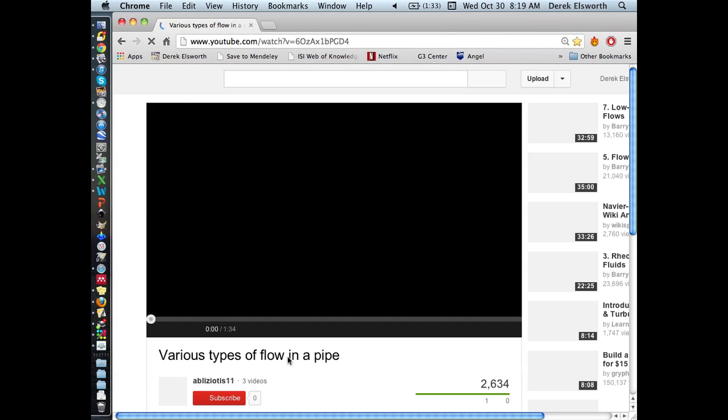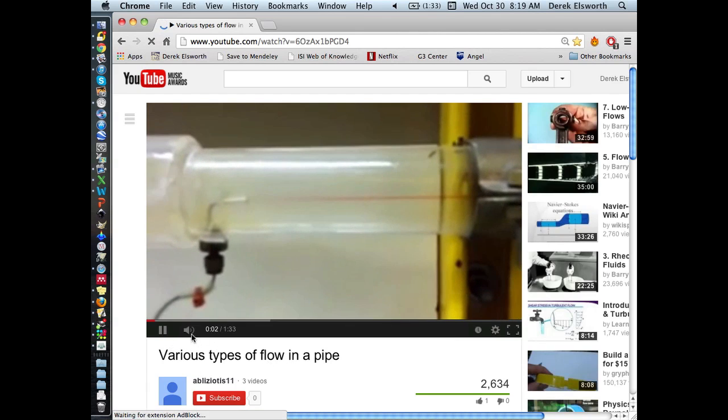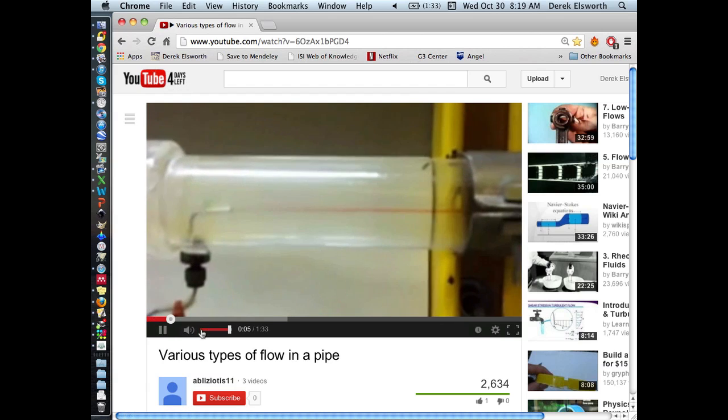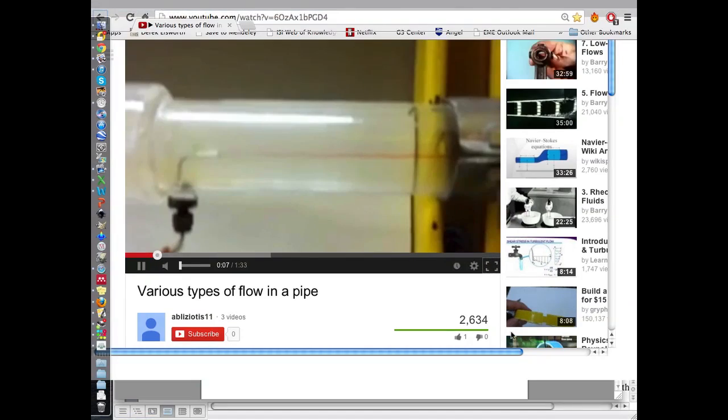And so it's during this transition from laminar to turbulent flow that we talked about. But this was just flow in an acrylic pipe, presumably quite smooth walled. But as you increase the flow velocity, which is what's happening in this, instead of this uniform, nice single pencil line bead along the length of it, you get this warbling in it. And this is just in the center of it. You can imagine if this is the case in the center, if you move the location of the dye tracer close to the sides, you'd also see these warbles.